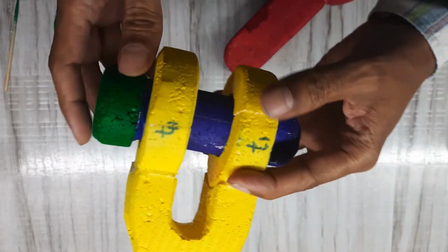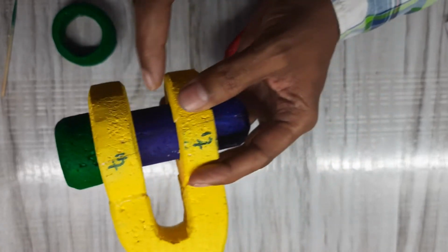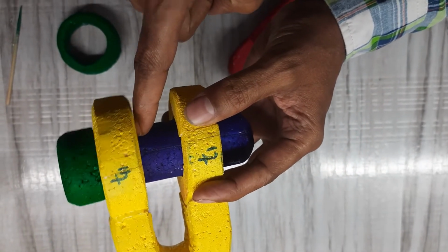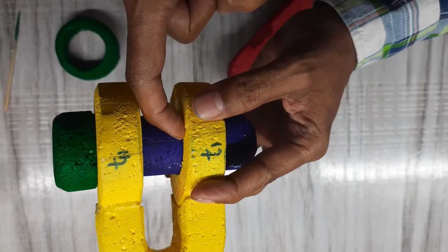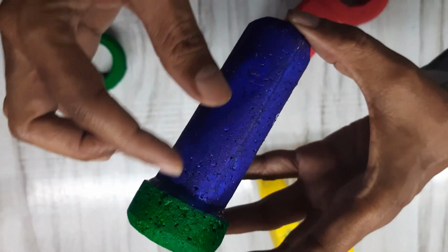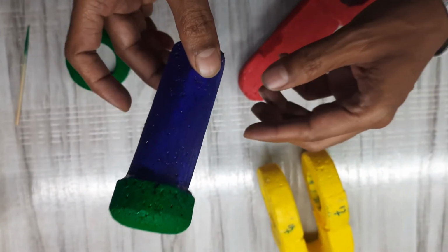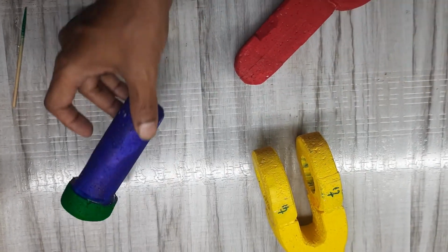Now the shearing will take place at two places. One from this position and the other from this position, and that's why we can say that this pin will be divided into 3 parts, which is called double shearing, and D1 is the diameter of this rod.